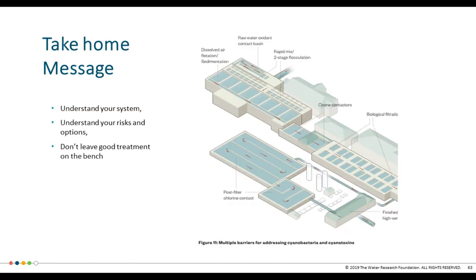And then finally, as Katie showed, we tried to summarize the concept of incomplete cell damage and delayed release, and really why this speaks to the take-home message, which is how important it is to understand your system and the capabilities of your system, to understand which treatment option is most applicable to you. If it becomes that you need to use a release and treat method, it's really important to understand the risks associated with that method and the threshold concentrations of oxidants that need to be around afterwards, either in follow-up treatment or remaining after the lysing of the cells occurs, to make sure you have effective treatment.